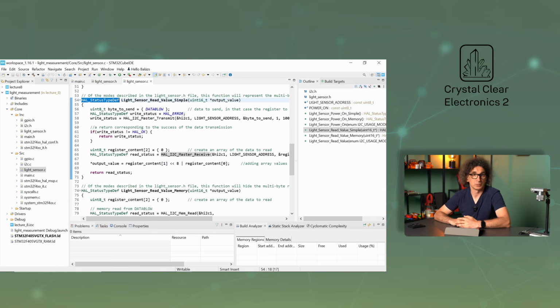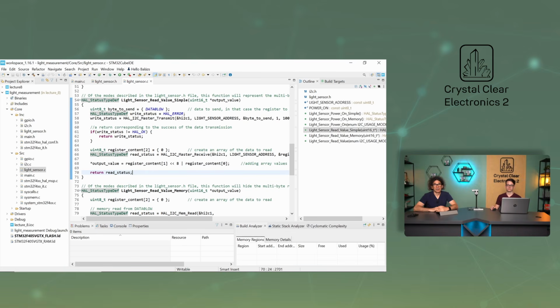We've managed to write this in one line, which can be useful because it is much more transparent for the more experienced programmers, but beginners may have difficulty interpreting the many operators. The transformation to a 16-bit number is done on the right side of the equation. Take the top byte from the array and shift it 8 bits to the left so that it is in place, while 8 0 bits appear below it. Here, we insert the lower byte with the OR operator. And on the left side of the equal sign, we store the data in the pointer.